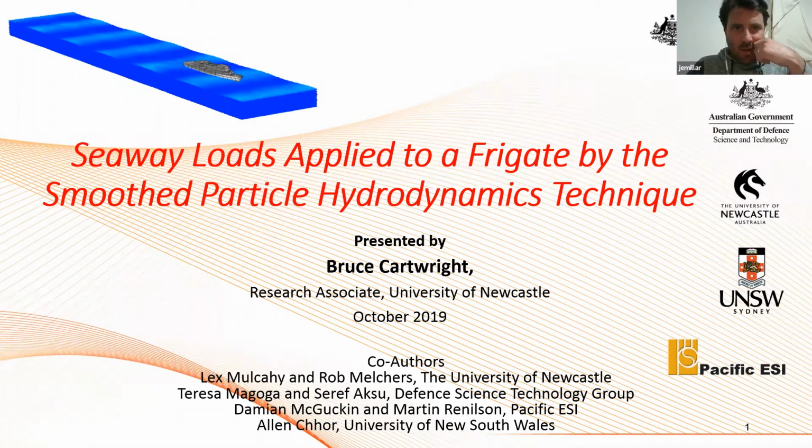And from Jason McConaughey, performance of steep waves: do you achieve expected vertical and horizontal asymmetry for nonlinear waves? Yes, that's quite a good question about the way the waves are developed. We do get quite increased steepness as the waves get larger. They do adopt the theoretical trochoidal form, and they will actually break if we make them too large. So this all appears to be following the physics quite well. We get increased steepness with wave height to the point that the waves will actually break.